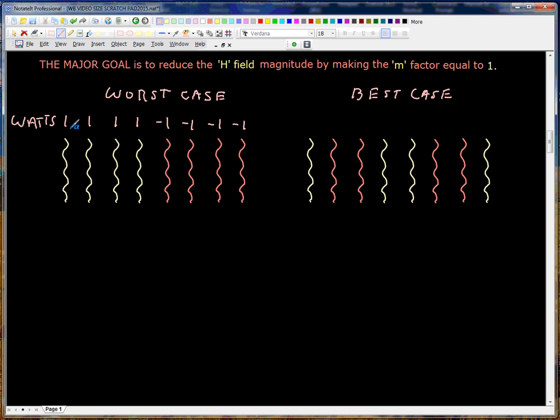I want to explain to you right now how we do that. Normally when you look at the H field, you use ampere turns per meter or ampere turns. We've converted that to watts. It's much more convenient to use. This is the wattage level. When we take power from the transformer, that's a secondary, and we use a negative value for that number. Another rule is that the sum always has to equal 0.